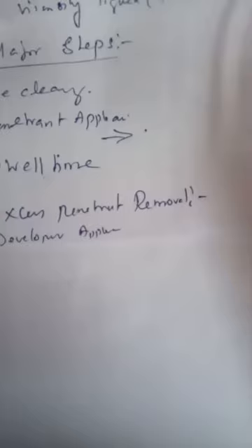There are two different types of penetrant. One is visible dye, another one is fluorescent dye. Visible dye is a bright red or pink liquid viewed under standard white light, ideal for field inspection purposes. Fluorescent dye contains fluorescent particles that glow under ultraviolet light, offering high sensitivity for detecting micro cracks, for example in aerospace engineering and precision engineering.